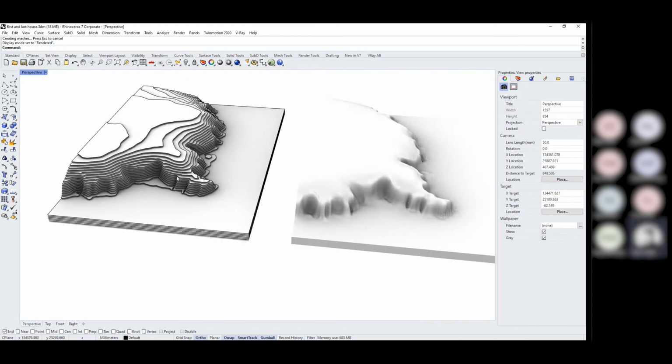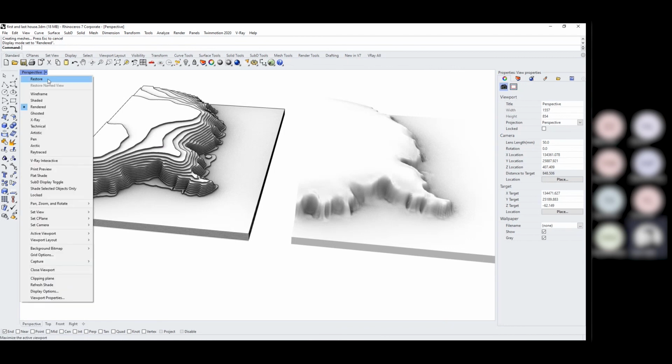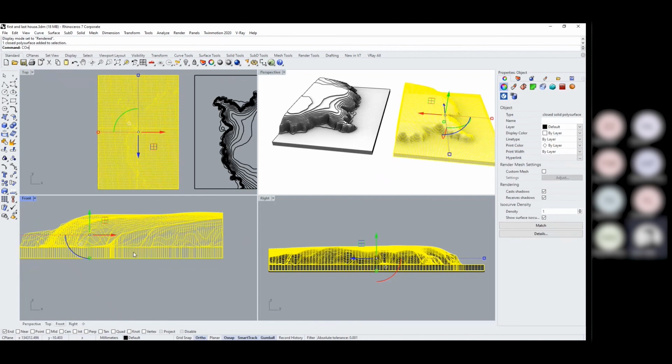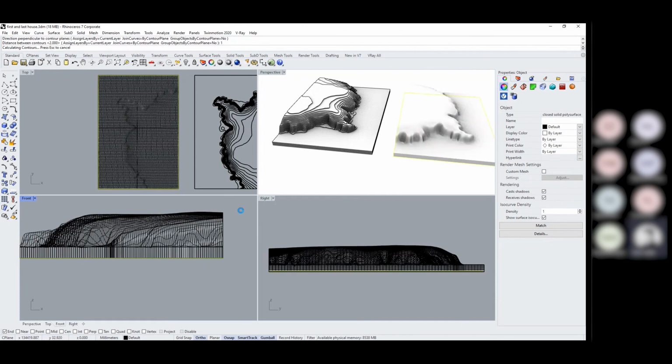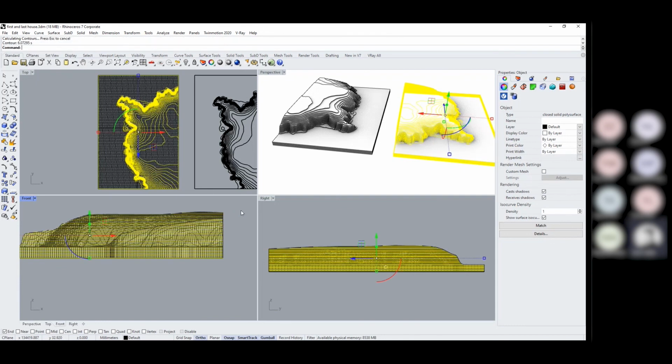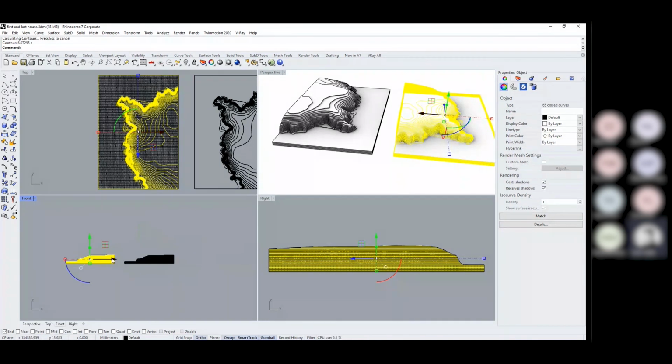And again, if I weren't happy with the level of detail with that, that's super easy to resolve. I'll just make another one. So let's say, for instance, I'll select my object again. I contour it, select it from bottom to top. Maybe I want to do it every 1mm. Maybe I want to add more resolution in. So I'll type in 1, hit enter. You see it's a significant number of contours this time.